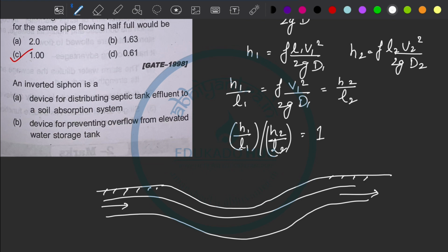So how can the sewer go through the water? There is water filled here. In this case we use inverted siphons, which are the opposite of a normal siphon. Another thing to focus on is that the pressure here should be greater than atmospheric pressure.